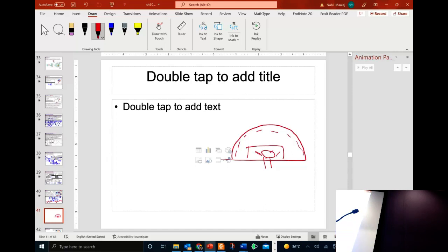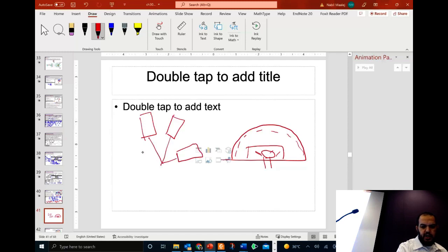So I looked at the detectors that were all connected to this PCB board. And I said, it's strange, they are all connected to this PCB board, so there must be something wrong in the circuit of this PCB board. And what we found was the grounding. Usually when you have many boards, let's say one board here, one board here, one board here, you always have to bring the grounding to one single point. It's called a star pattern. We found that one of the boards was connected in such a way that it caused a loop in the ground.